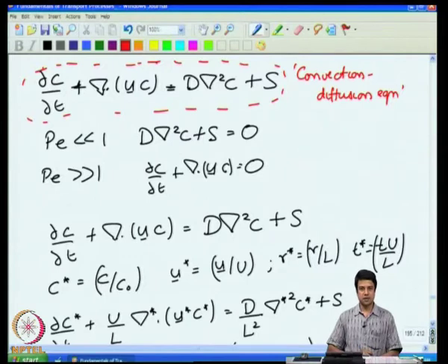So, this is a general convection diffusion equation, and the actual form of the divergence and the Laplacian do change. They do depend upon coordinate systems. And I showed you how we can derive these. We derive these by writing a shell balance over a shell whose surfaces are surfaces of constant coordinate.